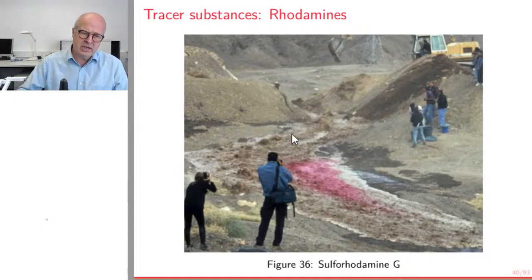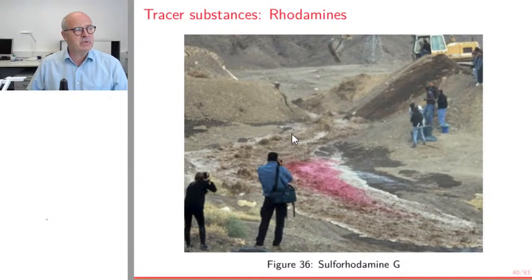If you work in groundwater, you should use uranine. It's wrong to use sulforhodamine in groundwater because most of it will be sorbed on the sediment. It's wrong to use uranine in surface water. This is like a beginner's mistake. There might be situations where you have to use uranine in surface water because there are no other options, but you shouldn't in a normal case.